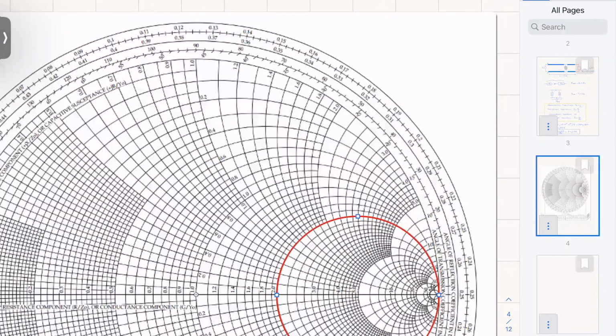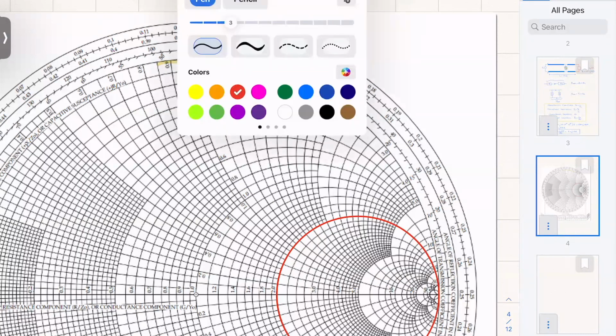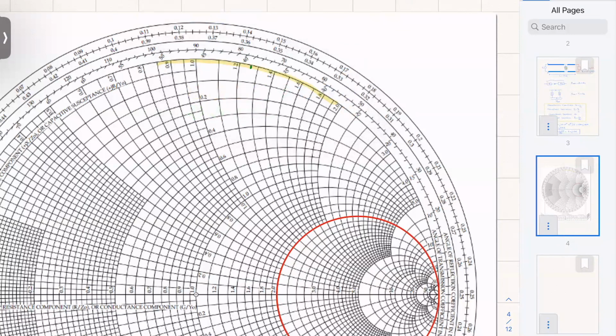So I'm going out here to find 1.26. So this is 1.2, this is 1.4, this is 1.3. Therefore, 1.26, use green, is going to be here somewhere. And therefore, I'm drawing this circle. All right, it's going to go there. And I find that they intersect at this point. And that's my impedance. Okay, normalized.